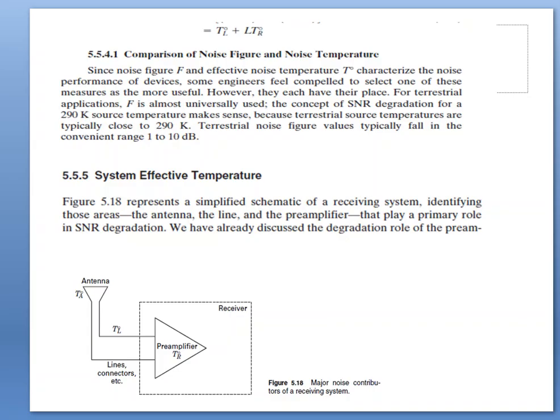Assume that an antenna and the receiver are connected via nothing more elaborate than a lossy line. Then Ts and Ts dash are related to the line loss factor L. That is, Ts dash is equal to L Ts and PR dash is equal to L PR. When computing these receiving SNRs by using the relative reference condition definitions for the power received and the system temperature, there is no difference in the result compared to using the original, because the factor L appears in both numerator and denominator of SNR and hence cancels out.